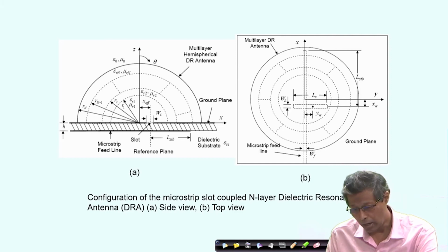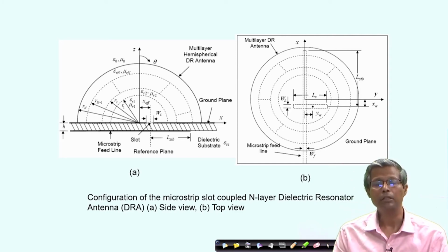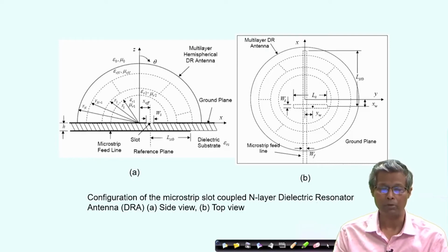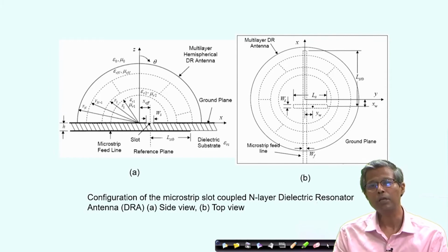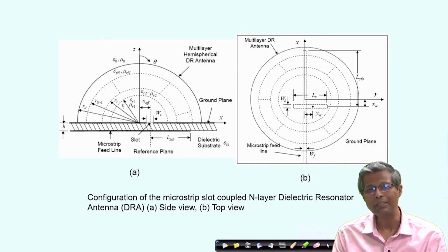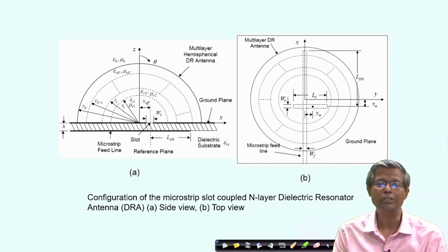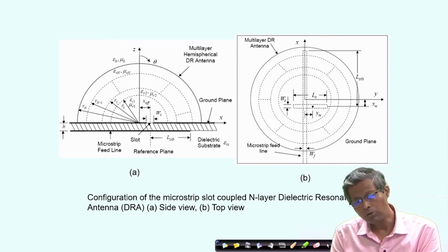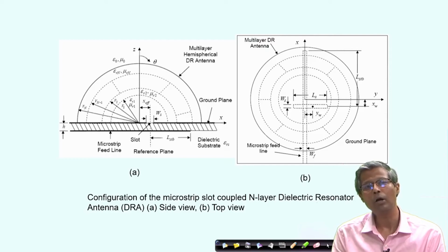and the reason why we would consider a multilayer structure is that, as we discussed previously, it offers a relatively much wider bandwidth compared to a single layer DRA. In addition, it enables a matching in environments which are more challenging to match using a single layer DRA. So, those things we are going to see as we progress through, but it will also explain why the knowledge of the modes which we have learnt in the context of the